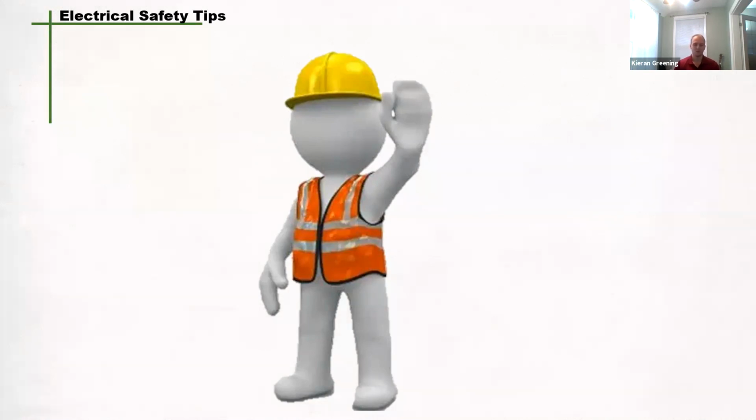So we want to store our materials and equipment more than 10 feet away from overhead power lines, just because there's a chance of arcing. It depends. Some people might have to climb on top of different stacks of pallets or anything like that. So if there is quite a height to it, it's best practice to store stuff quite a distance away.